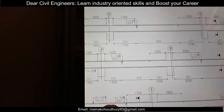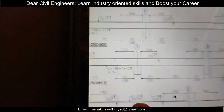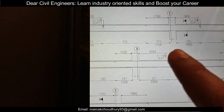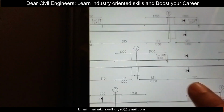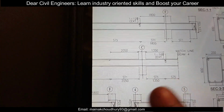And in the second span, these 2 bars of 16 mm, which are all through, will continue, and 2 bars of 16 plus 1 bar of 12 in the bottom will also continue. Only here we'll have an extra bar of 1 bar of 16 mm dia. Here also this is a continuous span. Here also we have 1 bar of 16 mm dia, which is continuous. Again at the last span also we have 1 bar of 16 mm dia.